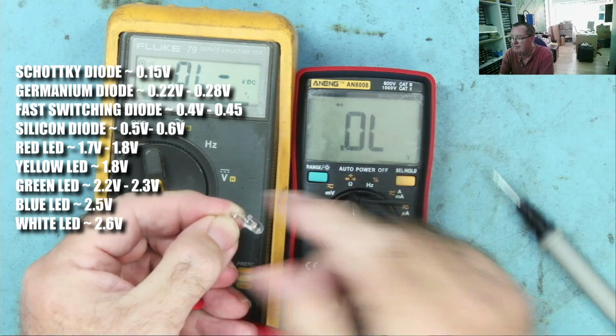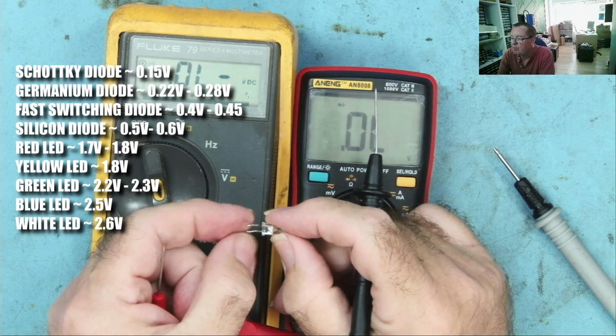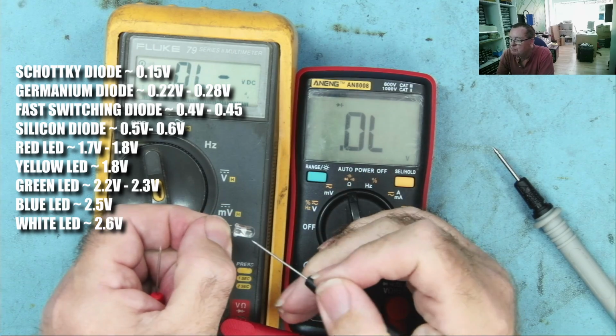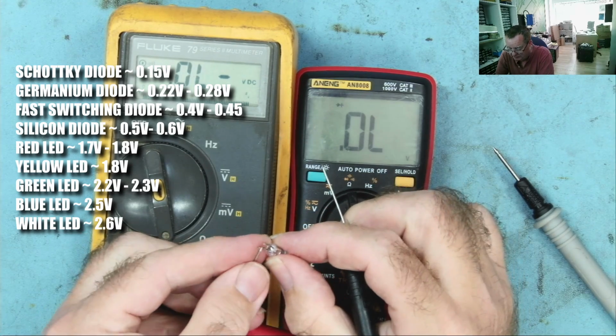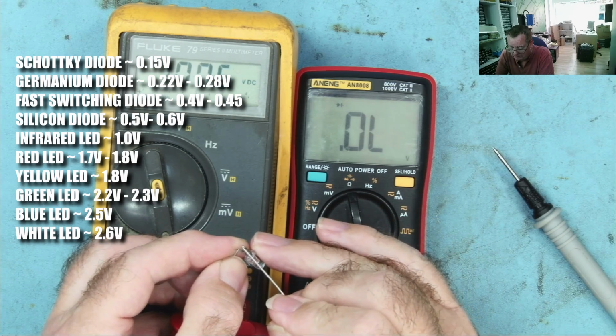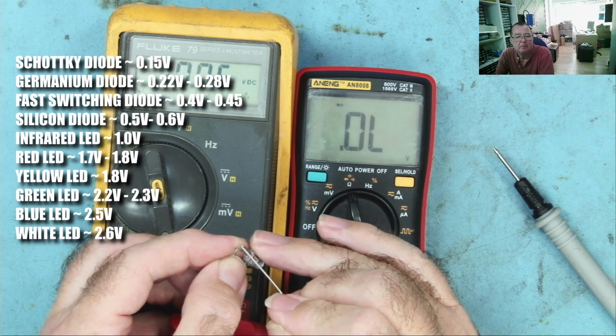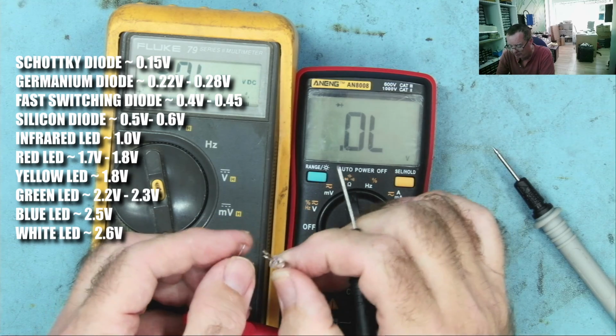You can get infrared LEDs also. This one is a pull, but I know that the anode will be the one with a small terminal inside it. So we can put our positive lead to it, and let's measure this one. And that reads 1 volt. Okay, so that's an infrared LED. We can't see it lighting up, but we can assume it is.